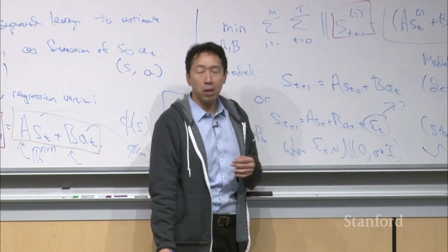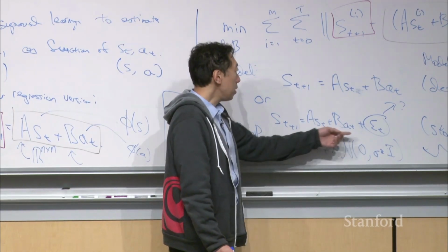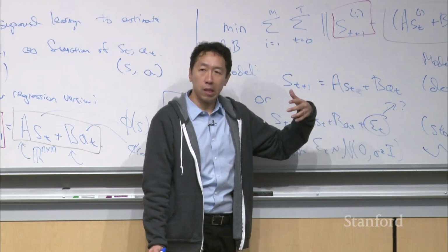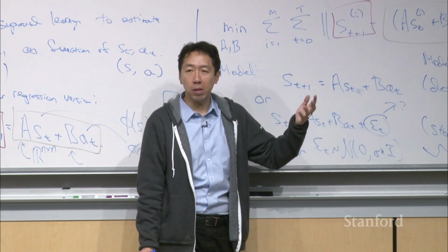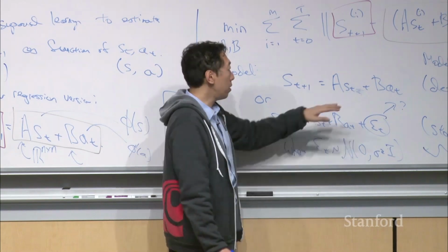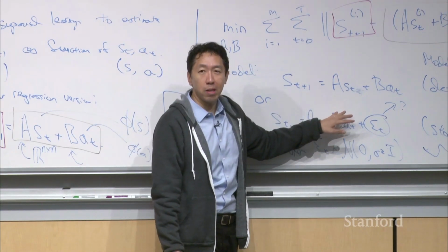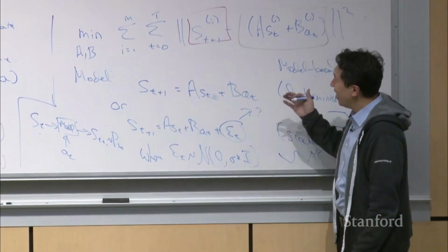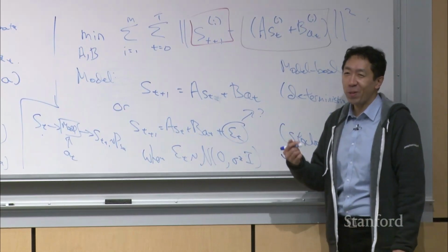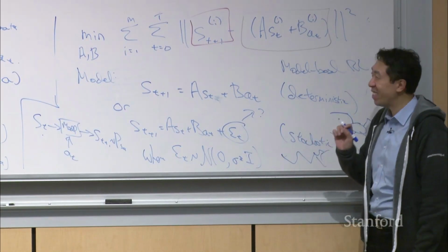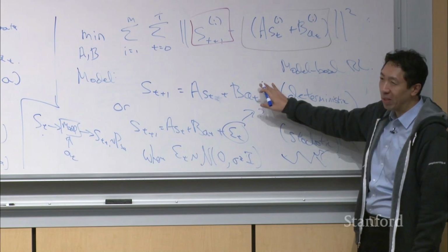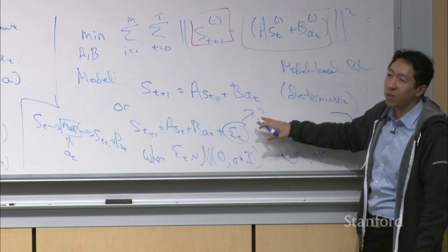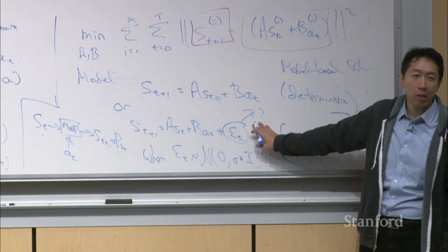Because if the policy you learn is robust to a slightly stochastic simulator, then the odds of it generalizing to the physical real world is much higher than if you had a completely deterministic simulator. So whenever I'm building a robot, with one very narrow exception, LQR, LQG, which we'll talk about next week, I pretty much never use deterministic simulators when working on robotic control problems, assuming I want it to work in the real world as well, right?